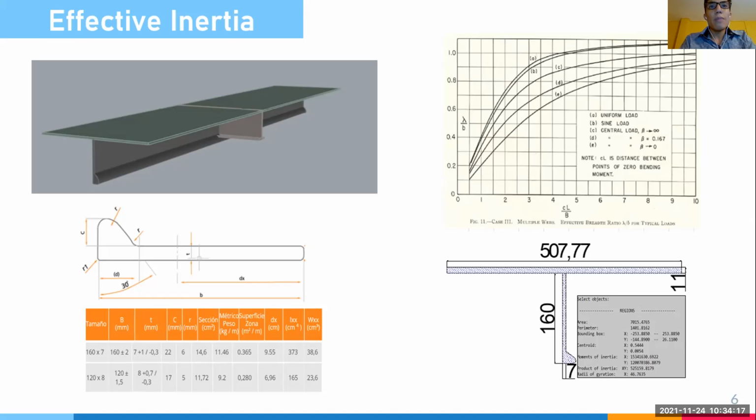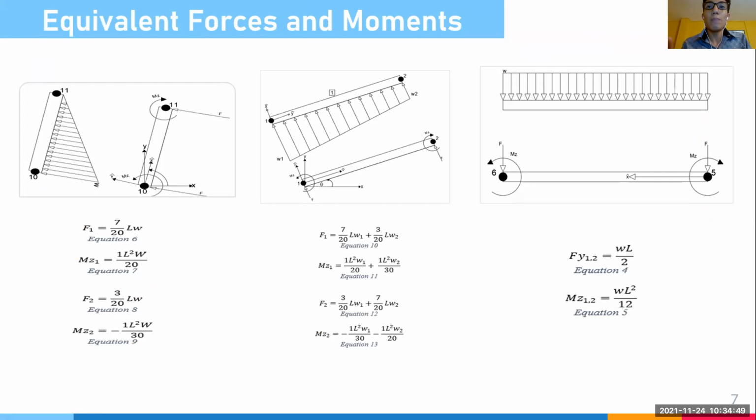Also, to obtain the global matrix, the matrices of each element are combined. According to the joint connections, the inverse is multiplied by the external forces and moments to obtain the global displacement in each joint. We need to convert our global displacement in order to get the axial forces and stress. And finally, using the polynomial equations, we can determine the shear force, bending moment, and displacement for every element, and then calculate the normal stress due to bending as well.